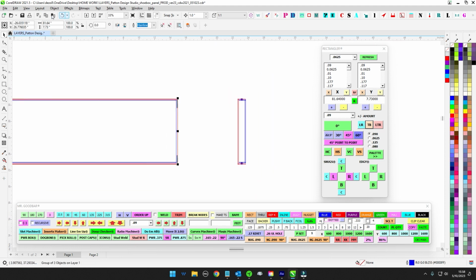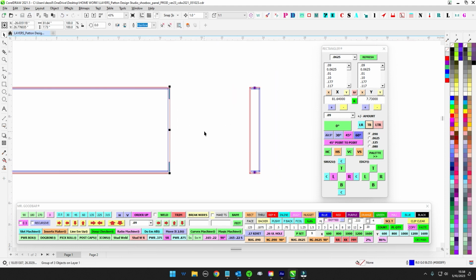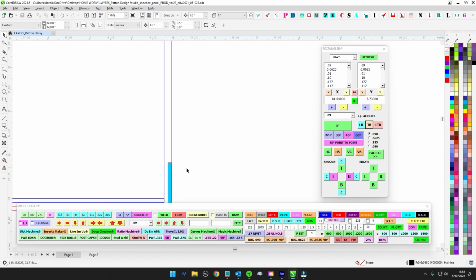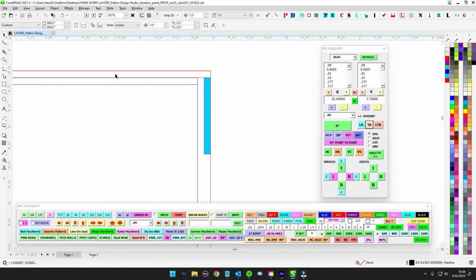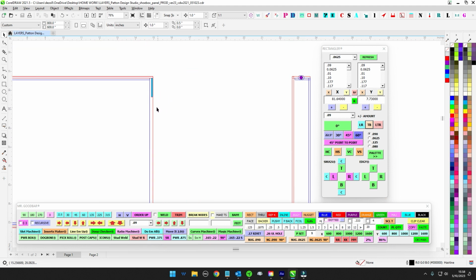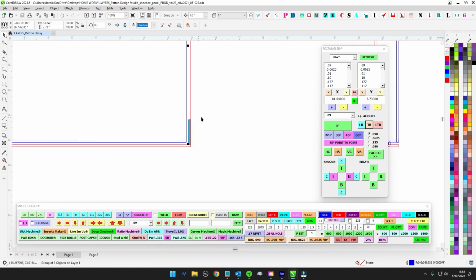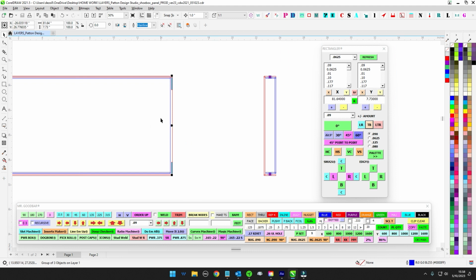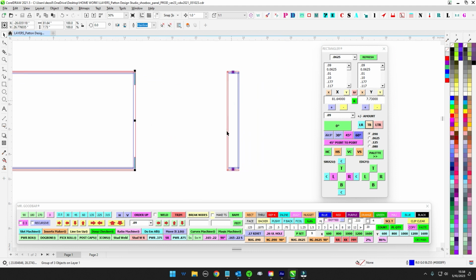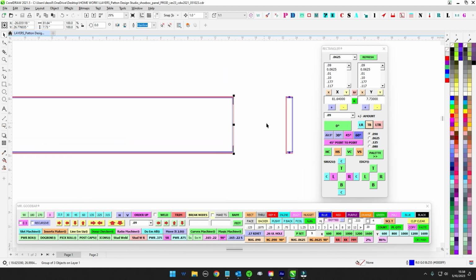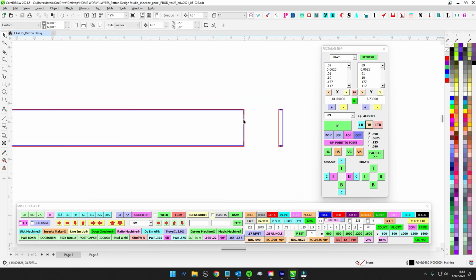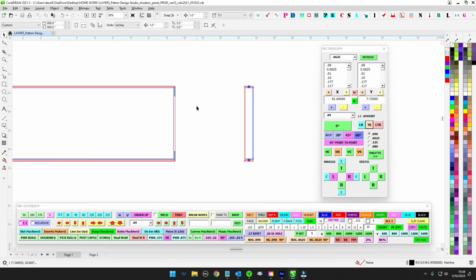And now we're good. And so now we have the representation of the front of a backer that fits with 090 clearance on the sides and the bottom with 0 on the top because gravity, it's going to sit there. Which means you have to be careful, because now your backer is not justified to the center of the face. You have this sort of offset for the backer. So you always have to keep that in mind, and it's important to do that. Okay, so now we have our backer and we have our side.